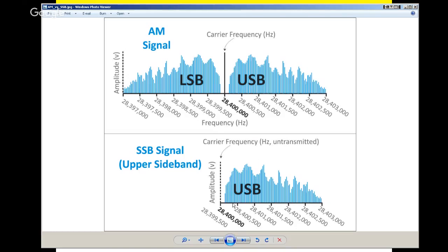In this case, it's only taking up 3 kilohertz of bandwidth, and all the information and all the power that's going into that signal is going into the upper sideband modulated signal. There is no carrier. The carrier, through the magic of electronics, is taken out. Once the signal is modulated, it's taken out, and all you have is this intelligible, or you hope it's intelligible, signal going out over the airwaves. So that's kind of the relationship between the carrier, lower, and upper sideband. Any questions on that?